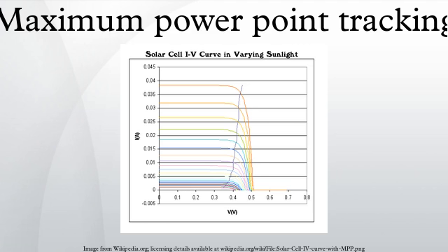In tabulated data it is often used to estimate the maximum power that a cell can provide with an optimal load under given conditions, P equals FF times VOC times ISC. For most purposes, FF, VOC, and ISC are enough information to give a useful approximate model of the electrical behavior of a photovoltaic cell under typical conditions.